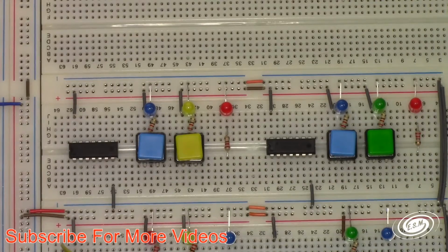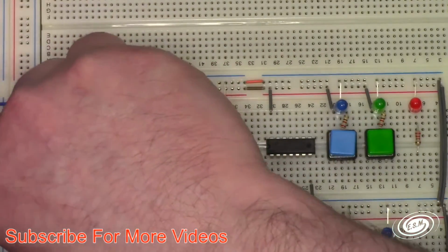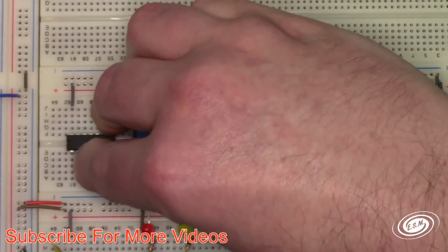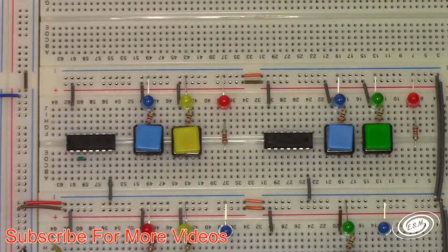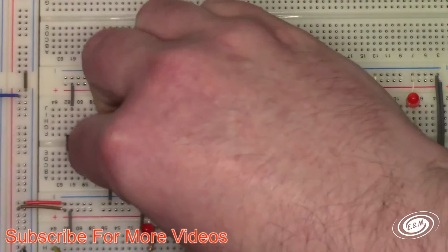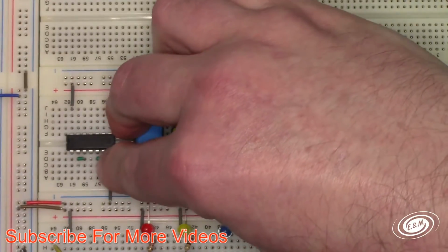Okay, so I'm going to tie input to pin 2 and 3, which is my A and B input, and then I'm going to tie together pins 5 and 6, which is my inputs for my second NOR gate.